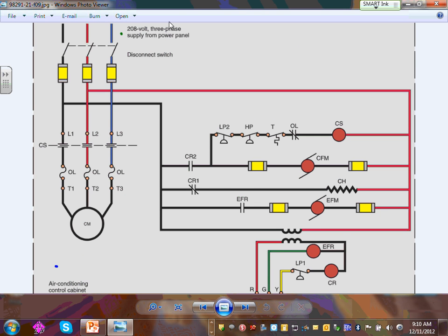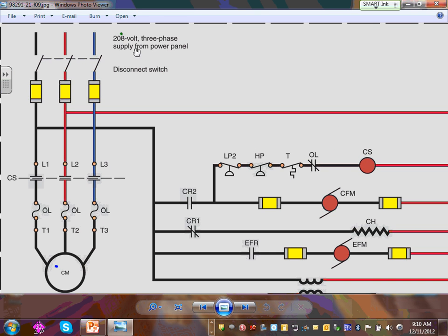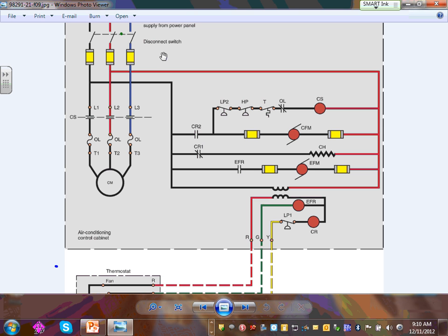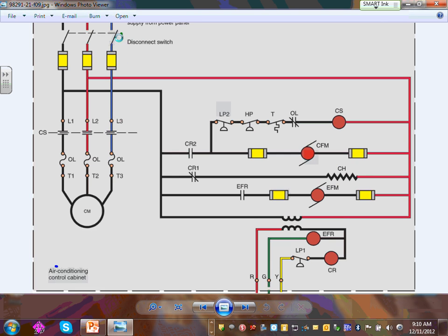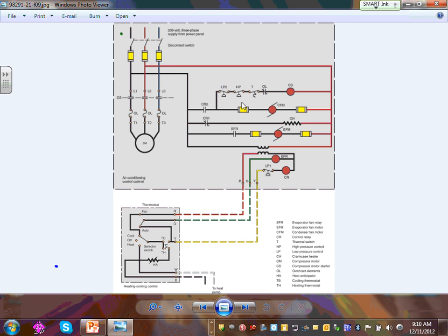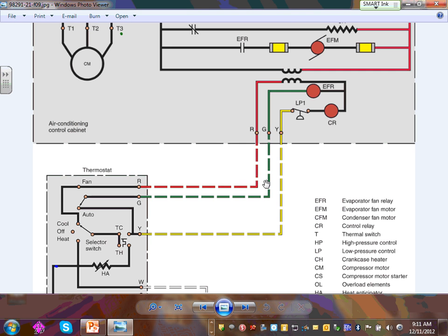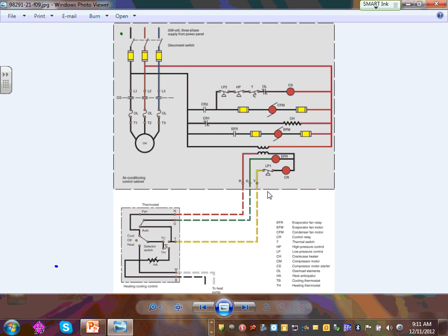You can see, guys, why a unit like this, 2A three-phase supply from power, is more than just a motor. There's tons of things inside that unit. So your job and mine, Jeff, is to come over here and provide that disconnect way at the top and the overcurrent protection device and the feeder. Everything else will be wired internally. We also provide the wiring, the thermostat wire, class 2 circuits here.